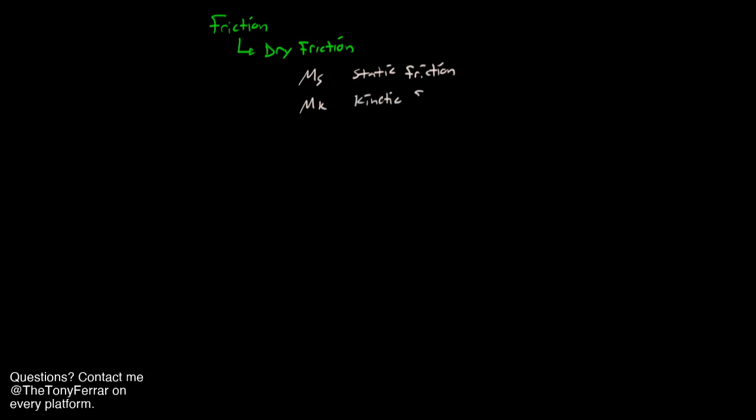And unfortunately, this is one of those times where the physicists and the engineers disagree on terms. And so static friction, I'd rather call it stationary friction because, as we know, static systems are systems that don't accelerate. They can be moving at constant velocity. So really, we can have a static system that is sliding as long as we're applying the force to keep it moving at the same speed. Then we'd still have to use this kinetic friction.